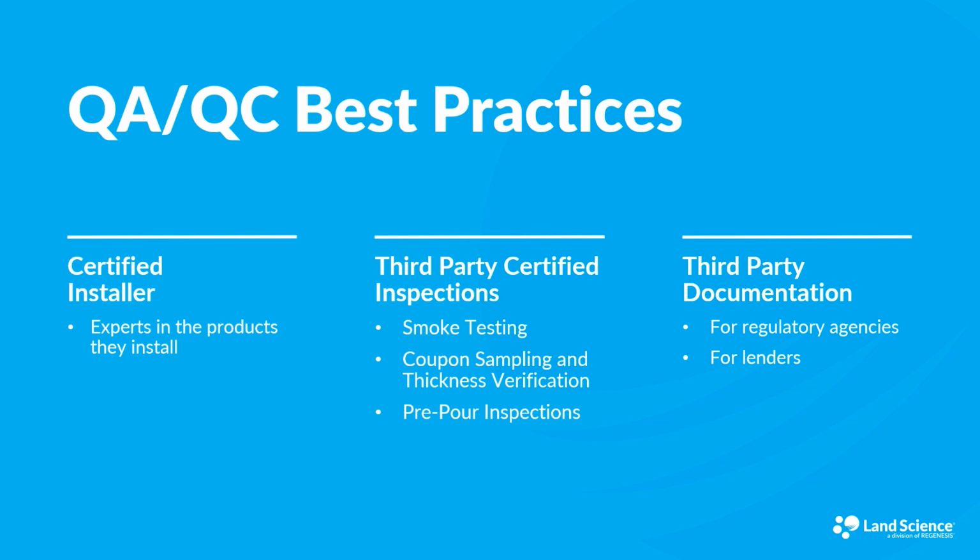Smoke testing is performed to ensure the integrity of the system and to find any pinhole leaks that wouldn't otherwise be seen with a simple visual inspection. United Consulting will typically be on site to document and oversee the installation, as well as the QA/QC process, which may include a pre-pour inspection to identify any damage that may need to be repaired prior to concrete placement.